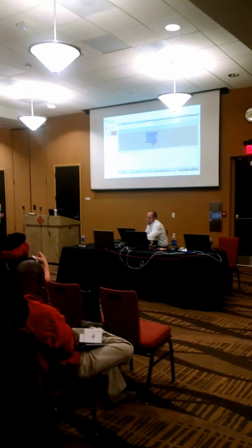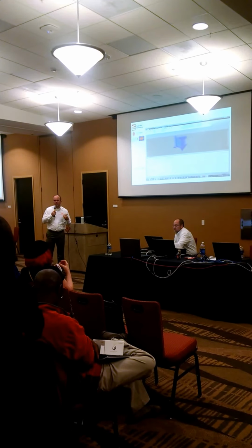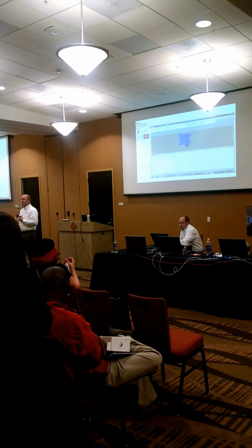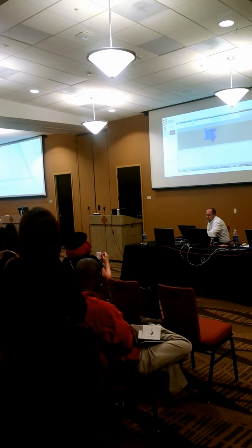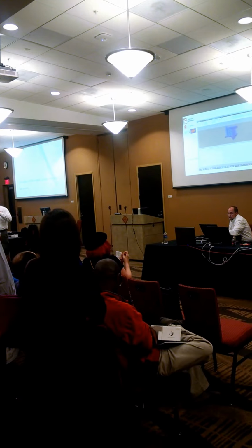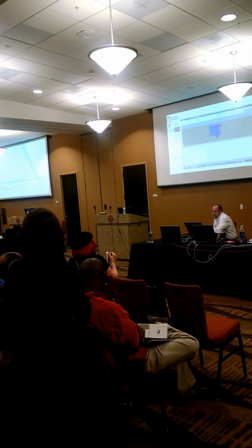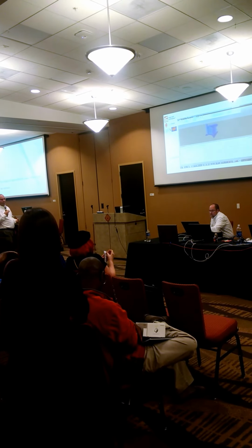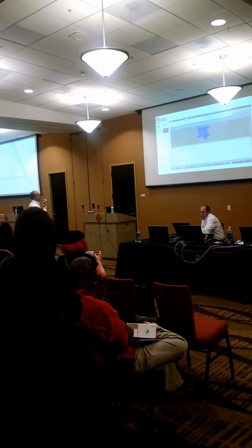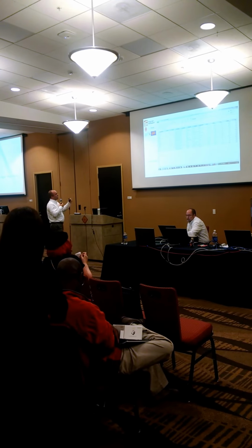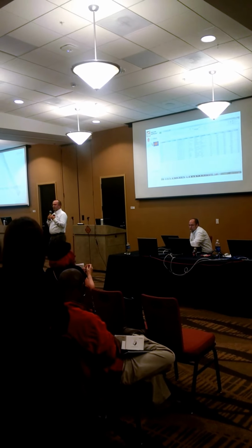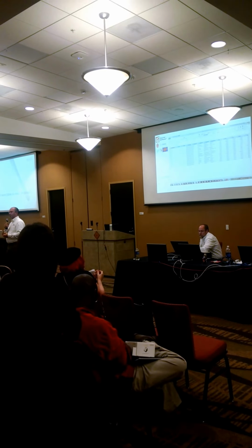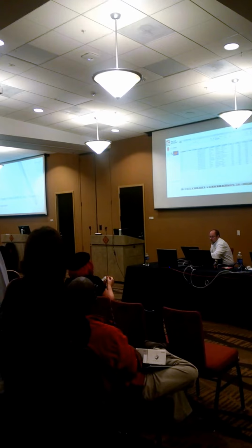Okay. We also took the model out to our Navisworks for doing some quick calculations, basically a quantity takeoff. So again, using Revit as the hub, if you will, to export that information out to various design tools that are accessible through our Autodesk Design Suite. We're able to come back through here and actually export some information that gets into quantities, amounts, Omniclass, different information, just by reading that model in that particular program.